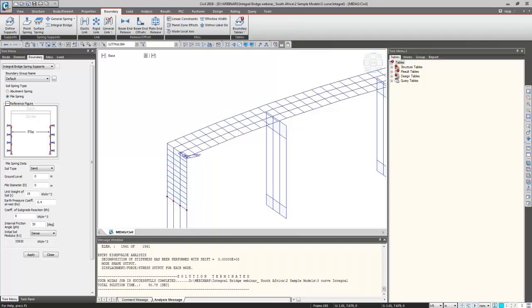So there is a question from Mr. David. In the reinforced frame analysis window, we are required to input surcharge and temperature gradient and system. I assume we will have to set them to 0 and only input them in the load window. Yes. If you have varied loads, you need to give them manually, if you have the girders and this one. What I've shown you is the quick generation from the wizard, and then you can later change it as per your project.